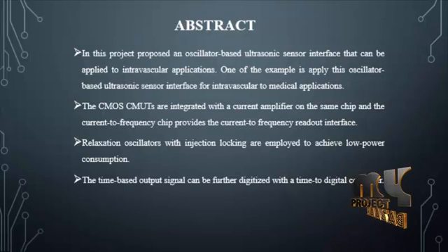The CMOS capacitive micro-machined ultrasonic transducer are integrated with a current amplifier on the same chip, and the current to frequency chip provides the current to frequency readout interfaces. The relaxation oscillator with injection locked are employed to achieve low power consumption. Also, the time-based output signal can be further digitalized with a time-to-digital converter.